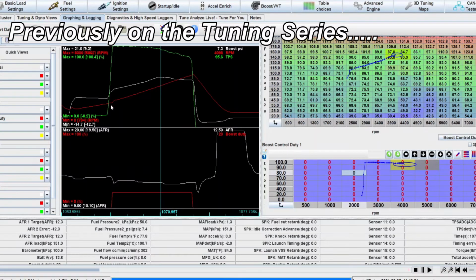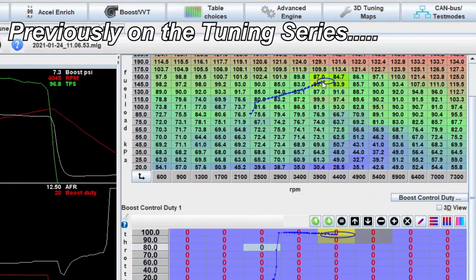Igniting the mixture too soon causes max burn pressure in the cylinder to be reached too early, before it coincides with the compression of the piston. Most engines want the max force to apply about 10 to 15 degrees after the top of the stroke, while it's on its way down in the power stroke.